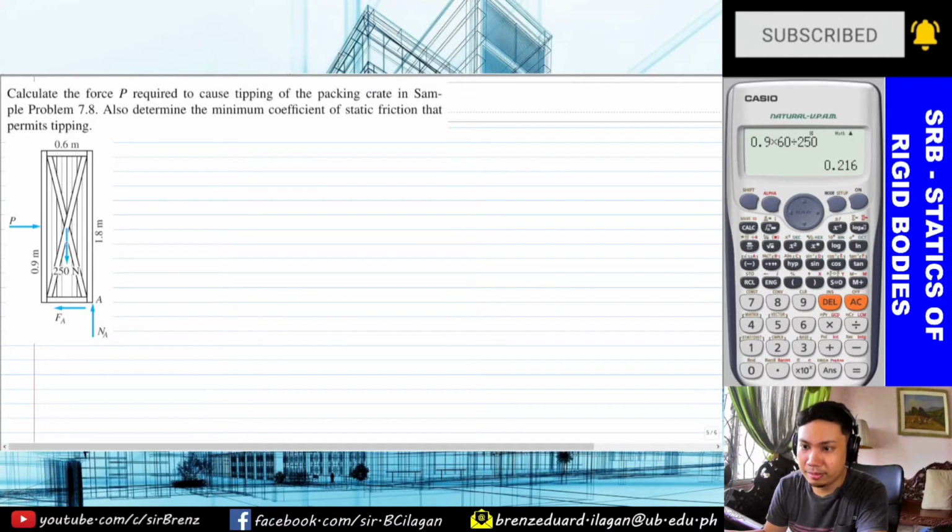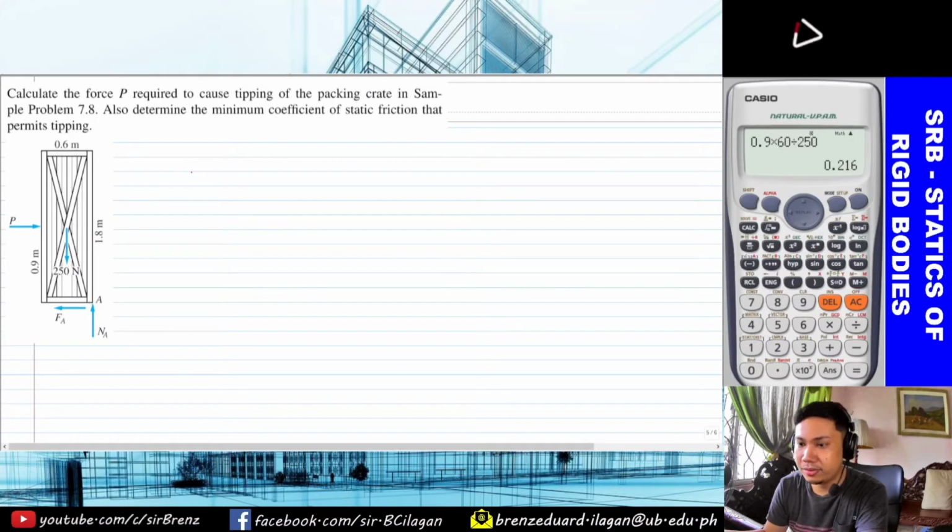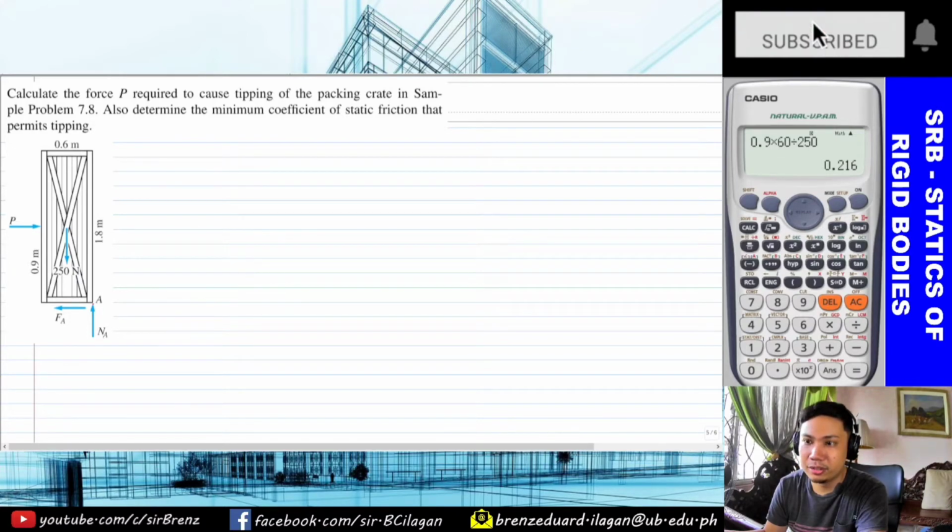So, this is its free body diagram. All the forces are specified there, and the point A itself, because it is about to tip over, so the maximum distance we consider is half of the crate, or the distance 0.3 from the center of the block. So we will just tilt it here.